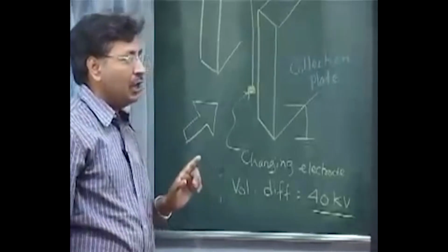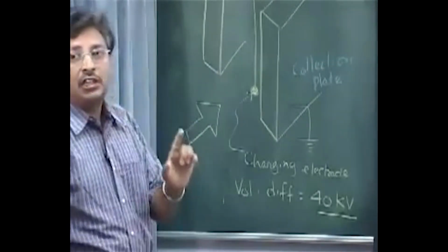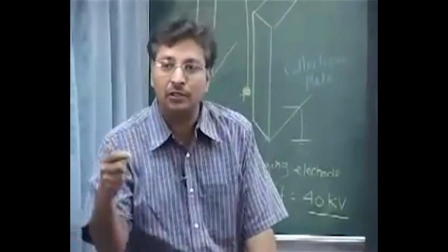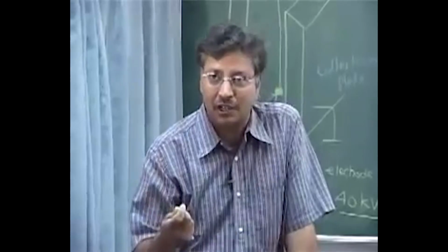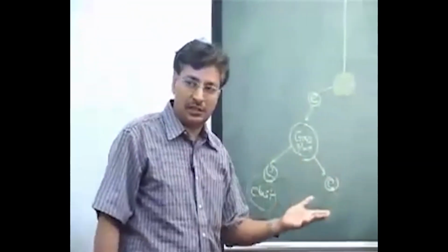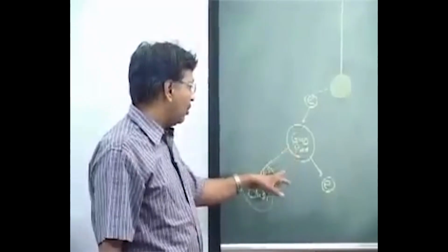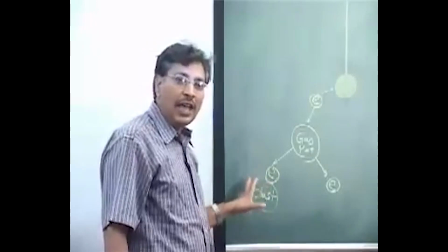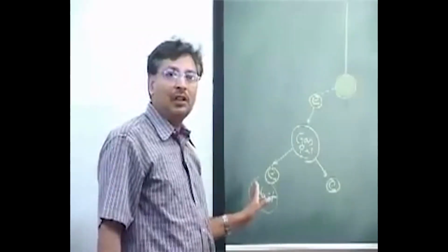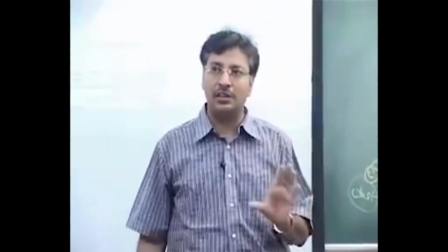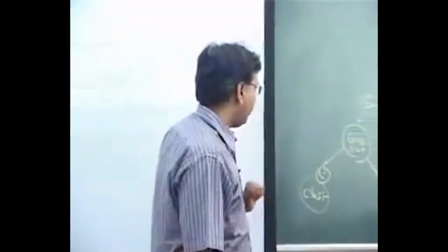So remember that ionization is taking place only for gases, because sometimes people get confused. Oh, okay, they hit the solid particles or dust particles and the particles become charged. Okay, where are the electrons coming from? But that's not the case. The thing which is getting charged is the gas, which is generally the air, or the flue gas. Then more electrons come out, and these electrons sit onto the dust particles, and these particles continue to travel because of the charge they are carrying towards the collection plate, and then they go ahead and sit onto the collection plate.